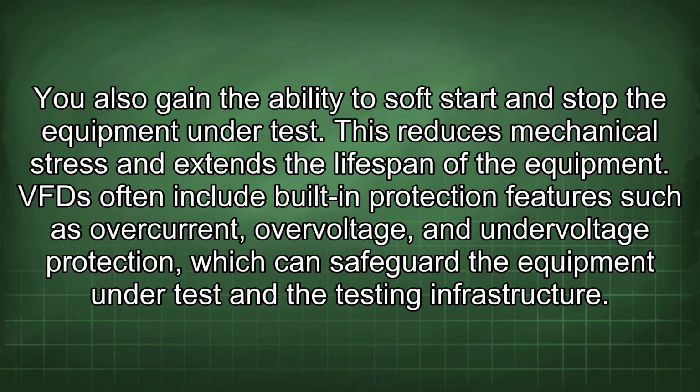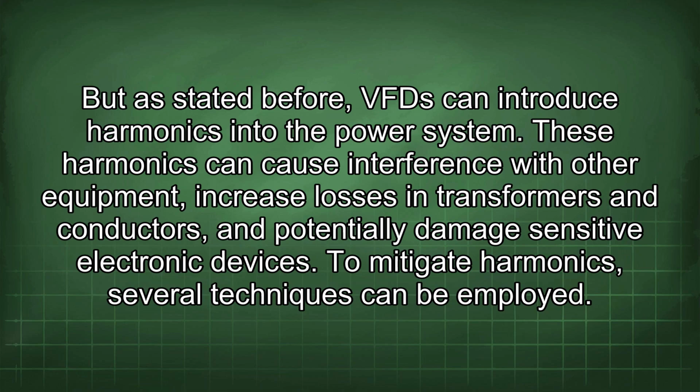You also gain the ability to soft start and stop the equipment under test. This reduces mechanical stress and extends the lifespan of the equipment. VFD often include built-in protection features such as overcurrent, overvoltage, and undervoltage protection, which can safeguard the equipment under test and the testing infrastructure. But as stated before, VFD can introduce harmonics into the power system. These harmonics can cause interference with other equipment, increase losses in transformers and conductors, and potentially damage sensitive electronic devices.